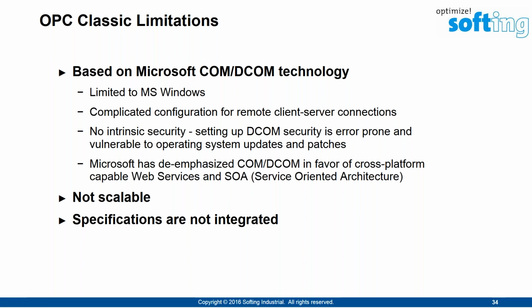OPC Classic is also not scalable, meaning that it can't run on embedded hardware platforms, for example. And lastly, the 3 specifications, DA, HDA, and AE, are not integrated. So you need a separate server if you want to support all 3 specifications. So one server for each specification.